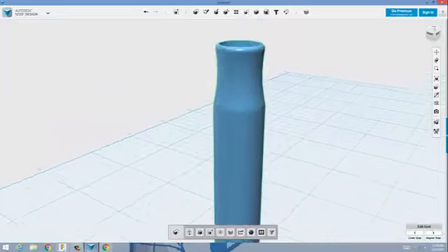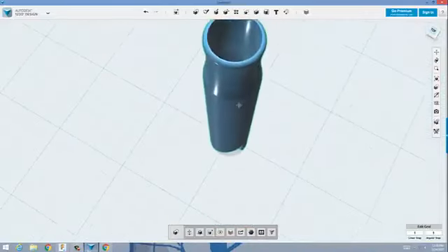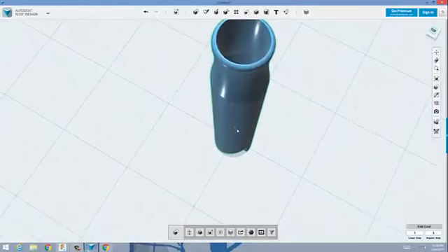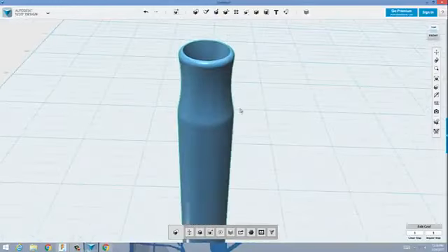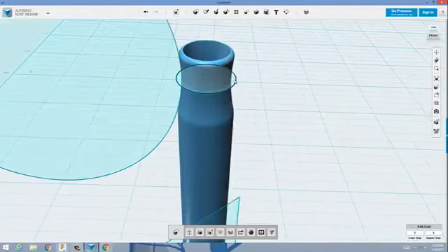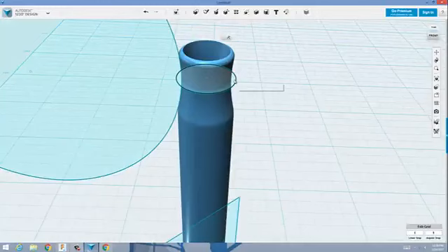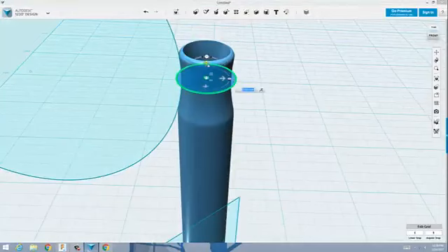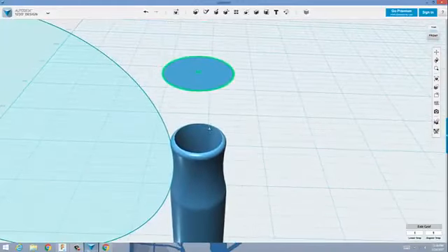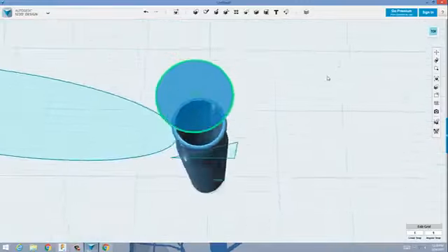We're getting very close. So now the piece that I need to do is to put a little piece inside there to create physics for my whistle. So I'm going to turn my sketches back on, because I'm going to reuse this circle that I had before. So I'm going to move it. I used a keyboard shortcut there. I'm going to move it along the z-axis, and I'm just going to do 20 millimeters. I'm going to go up here. We're going to draw a line on that circle.